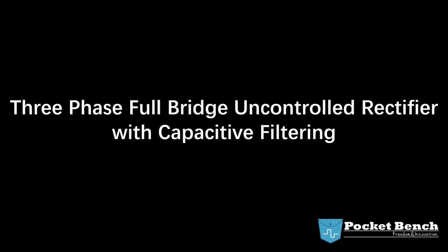The three-phase full-bridge uncontrolled rectifier with pure resistor load has very high DC voltage ripples. In order to solve this issue, a filtering capacitor is usually connected on the DC side to suppress these ripples. Such a converter is called a three-phase full-bridge uncontrolled rectifier with capacitive filtering.